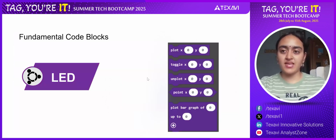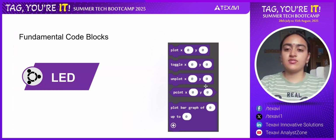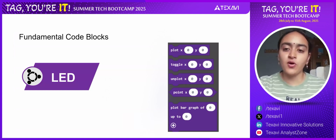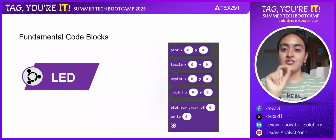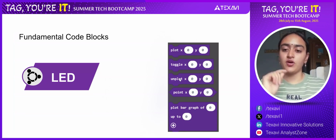So you saw on the basic that there was a panel which you could click and design what icon you wanted to appear on the microbit. But this is a little bit more advanced. So this treats the LED matrix as a graph, and you can plot X and Y coordinates. So X is the horizontal coordinates, and then Y is vertical. So you can choose which individual LEDs you want to light up and when. You've got unplot as well, so you can switch them on and off.